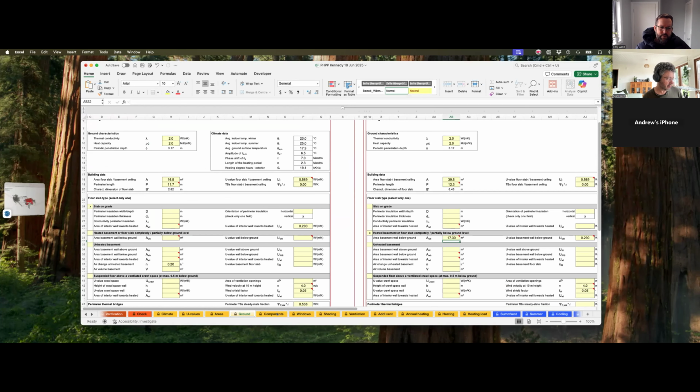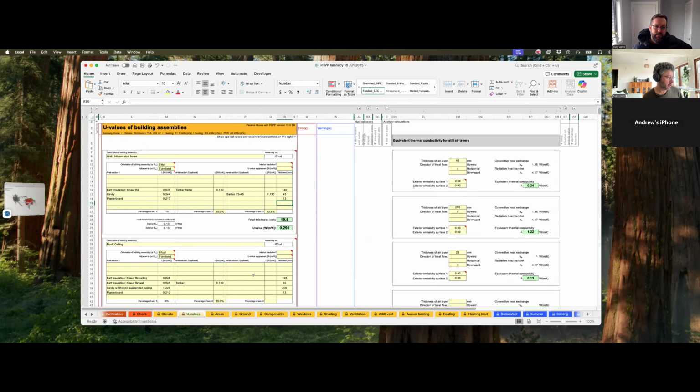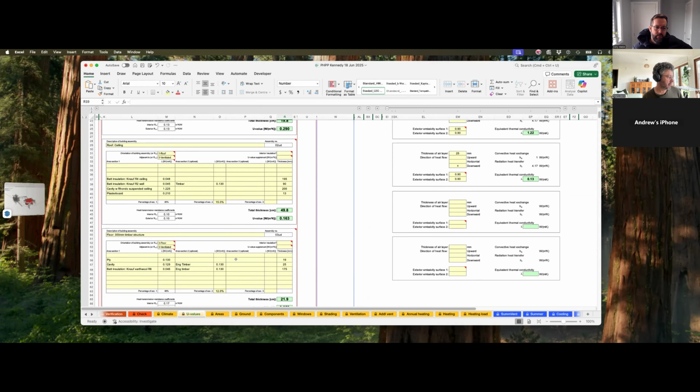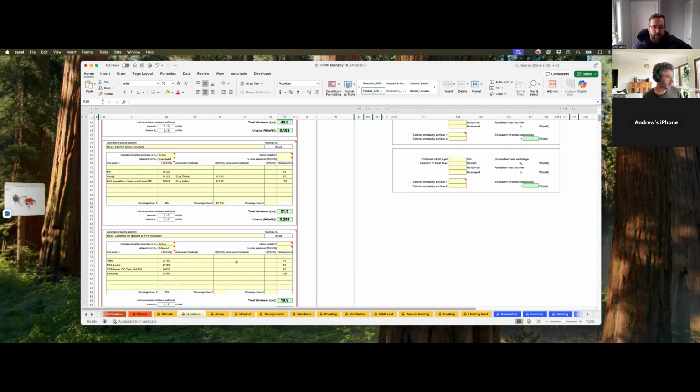Can I just ask the question again, Mark, on the slab thickness? The structural engineer had the suspended slab over the garage at 200 and the slab upgrade at 170. Is that a huge problem? No, that's not a problem from my perspective. It's only going to improve things slightly. Improves it, doesn't it? Yeah. So concrete on ground was 170, is that right? Yeah.